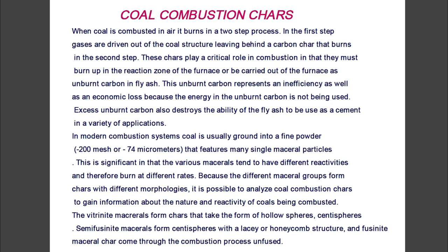It is possible to analyze coal combustion chars to gain information about the nature and reactivity of the coals being combusted. The vitrinite macerals form chars that take the form of hollow spheres, cenospheres. Semifusinite macerals form cenospheres with a lacy or honeycomb structure, and fusinite maceral chars come through the combustion process unfused.